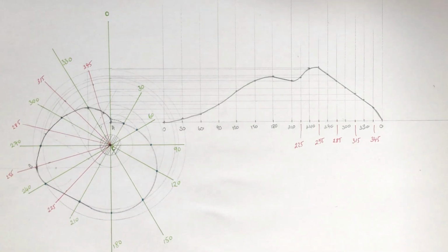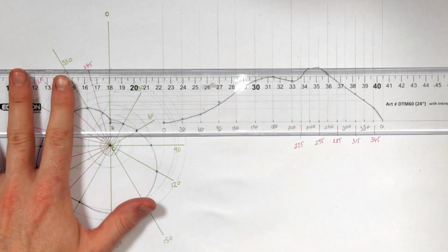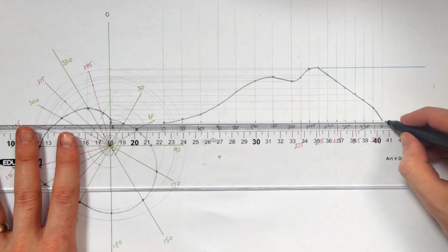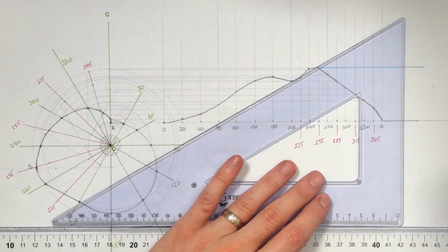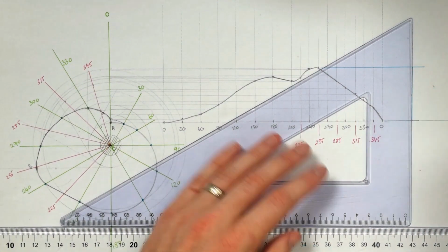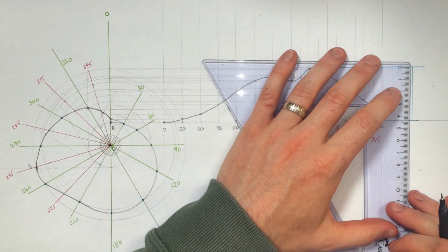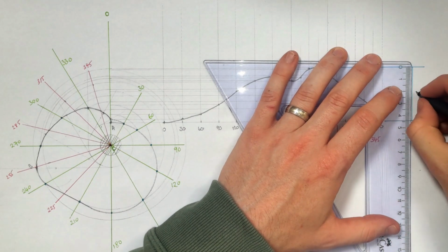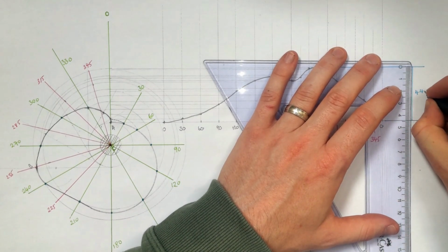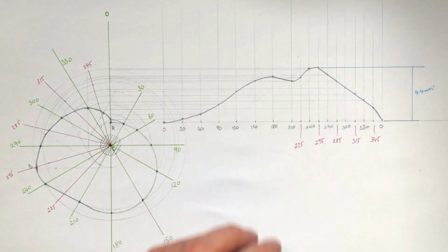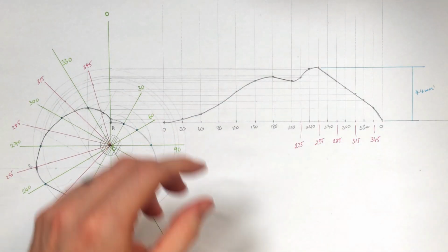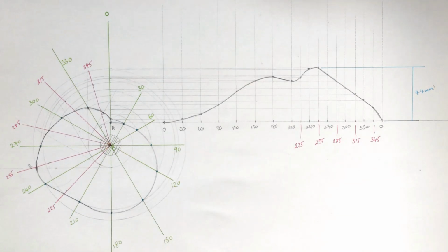Now the last part was to indicate how tall the displacement diagram is. So that is the highest point, here is the lowest point, and it's a case of measuring that. So for me, and there would be a tolerance with this, not everyone would have the exact same answers, it's 44 millimeters. Okay, so as long as you're within a millimeter or two of that, you should be safe enough there. Alright, so that's how to do that question there anyway.